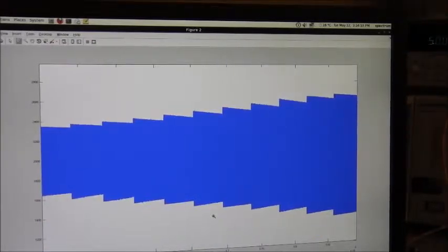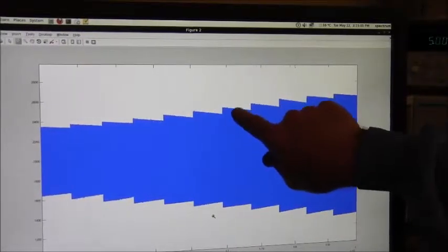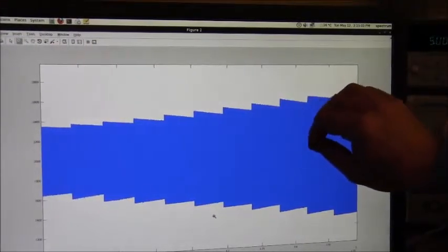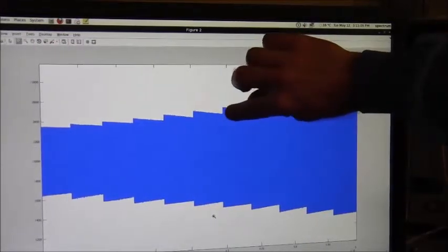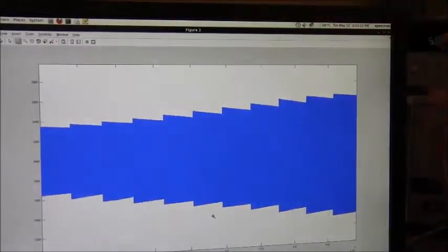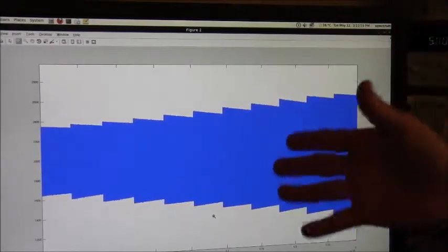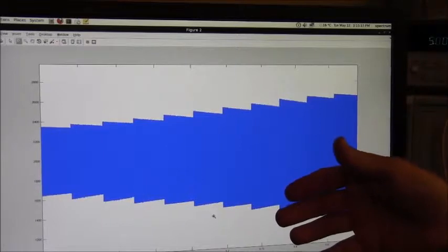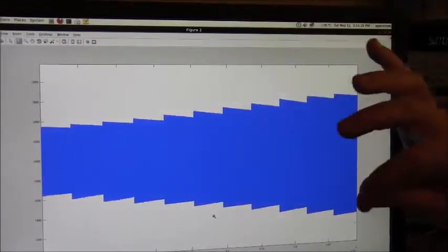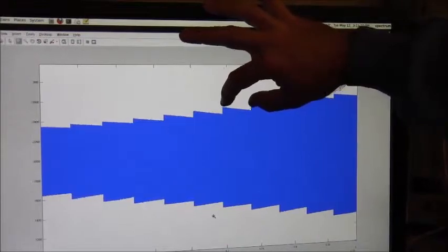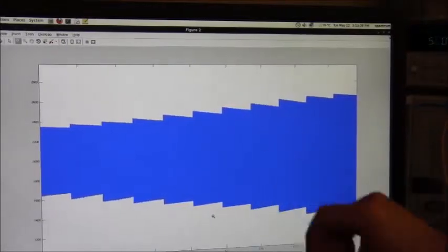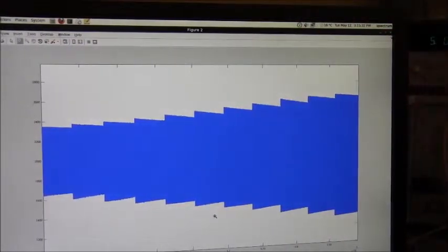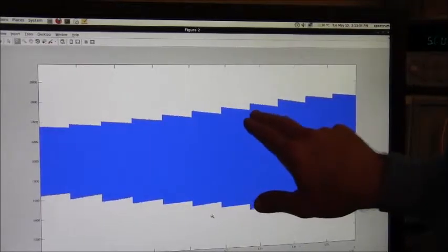So in this case, our AM modulation frequency is a little bit lower. So instead of having the rising signal on here, we're getting the falling part of the signal. So you can see this from there to there. That's one capture, and then the next cycle, after at the 5 kilohertz trigger rate, I'm actually starting a little bit earlier in the AM modulation's envelope. So I'm actually catching a little bit earlier and earlier and earlier, so I can actually see the jaggy. So from there to there is one capture. One capture is 4K samples.